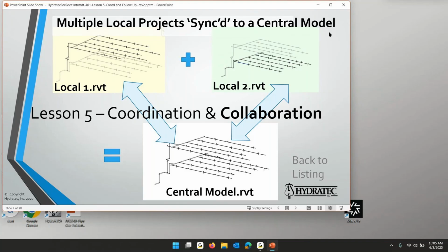The 4 branch lines drawn, or the 5 branch lines, let's say, drawn on the ground floor on the green computer, those get synchronized, added to the central model. And it's a two-way process. When the green posts or synchronizes their 5 branch lines for the ground floor, at the same time it collects the 4 branch lines from the second floor. And similarly, the second floor posts their 4 branch lines to the central model and collects the 5 branch lines that were added on the green computer.